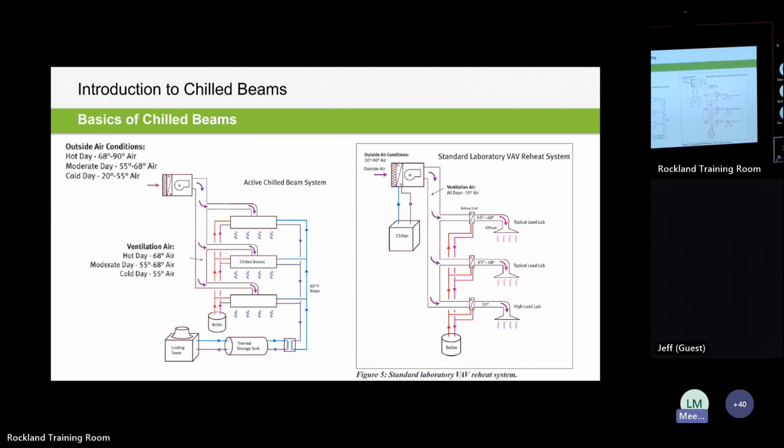Yeah, really all the chilled beam needs is the water valve adjustment and then the VAV, to your point. So the control modules themselves would be either the smart thermostat or the controller on the VAV box, and outputs would run to the water valves for the beams.